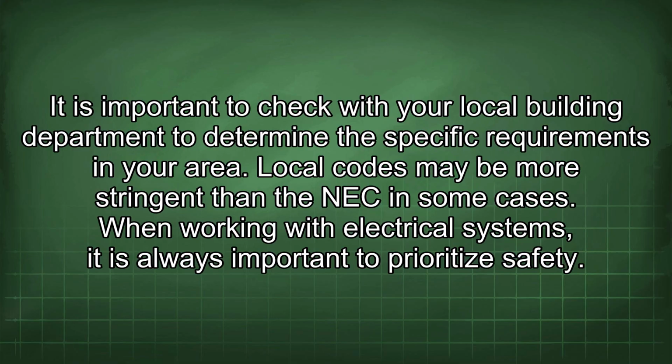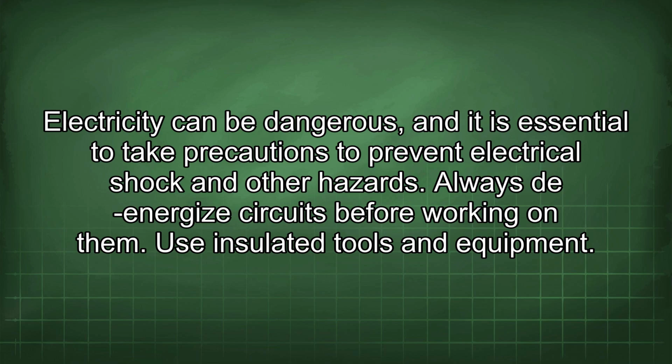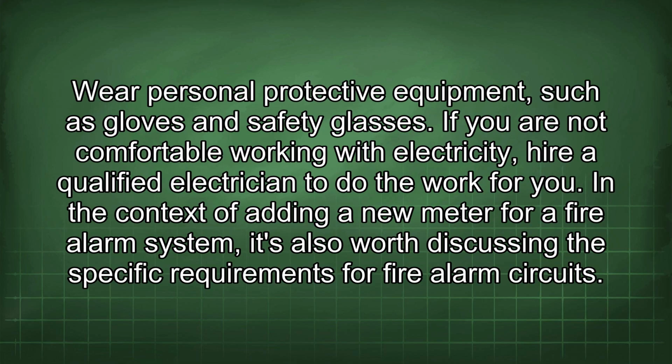When working with electrical systems, it is always important to prioritize safety. Electricity can be dangerous, and it is essential to take precautions to prevent electrical shock and other hazards. Always de-energize circuits before working on them. Use insulated tools and equipment. Wear personal protective equipment, such as gloves and safety glasses. If you are not comfortable working with electricity, hire a qualified electrician to do the work for you.